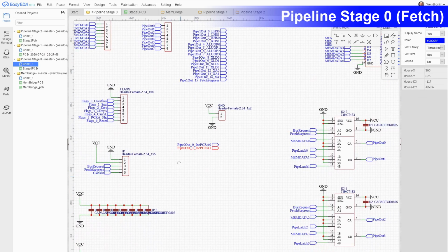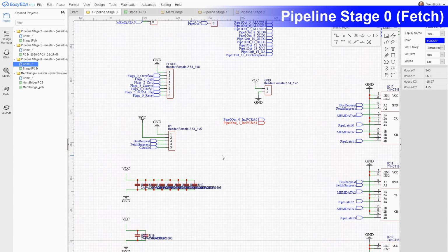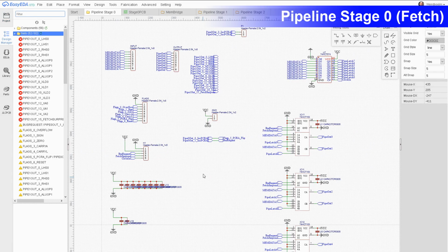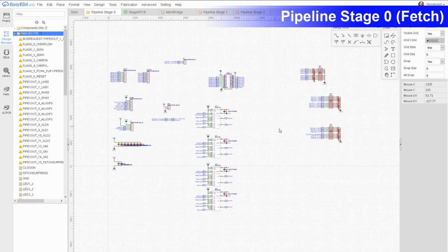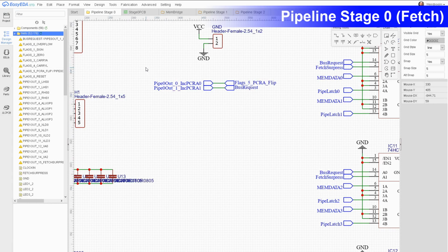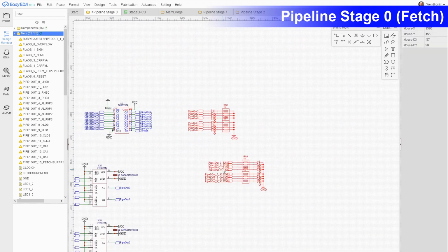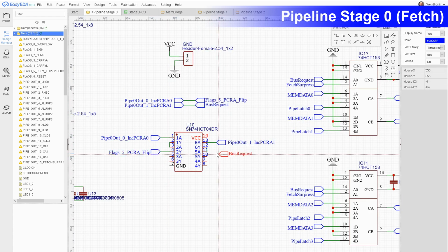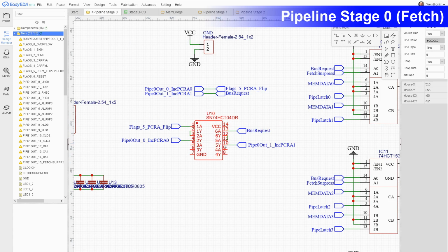Now what's a complicating factor here is these are directly resolved from the inputs. See what it complains about. All of these have to go. Now, actually I don't like this. This means the inputs are going to be asked to drive an extra set of LEDs. Okay, so we're passing this through 2 inverters and that will buffer it. I'm kind of surprised there doesn't seem to be a 7400 series chip which is just a buffer. I'm happy doing this though because I know I've already ordered a bunch of 04s.